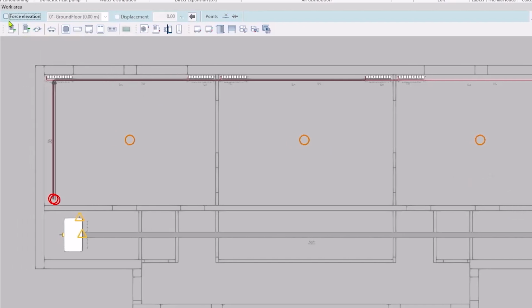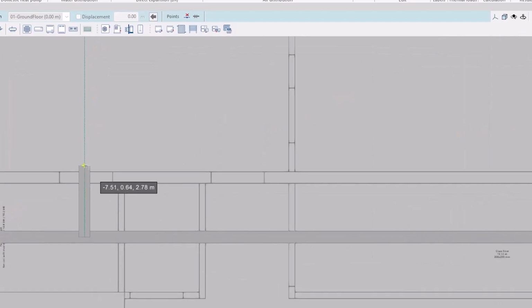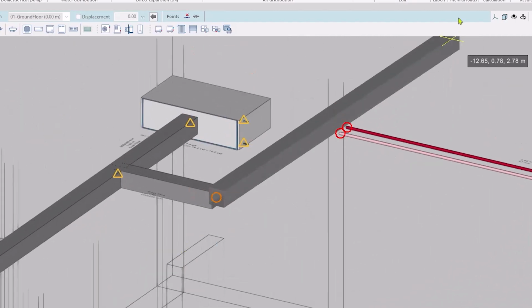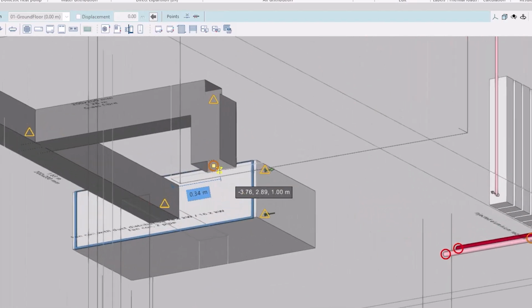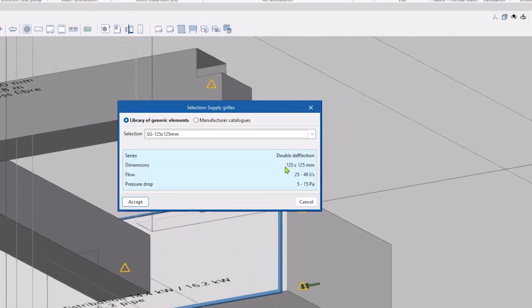As with the pipe diameters, we do not have to define sections. The program will analyse them and assign them to the different sections. We make a couple of connections per room with a final vertical section of at least 40 centimeters, with enough space to be able to solve the fittings and possible reductions up to the final grill.